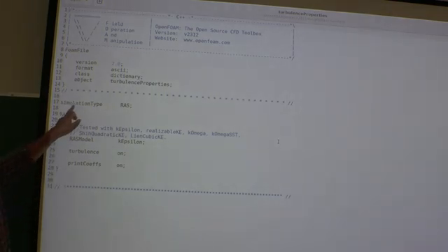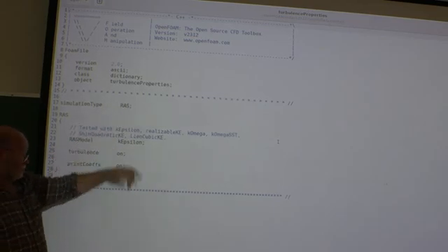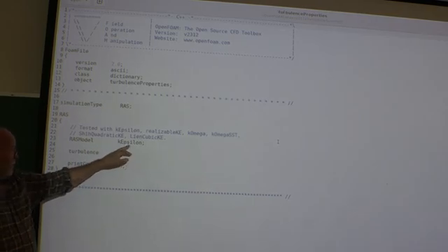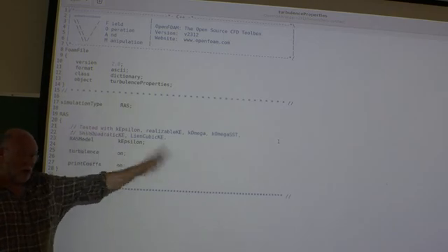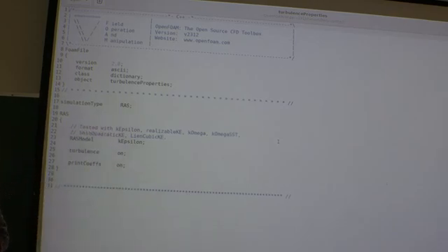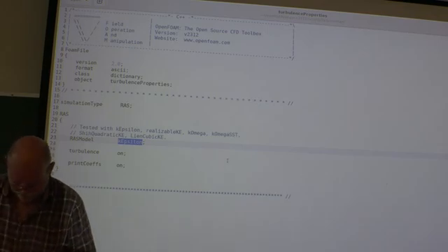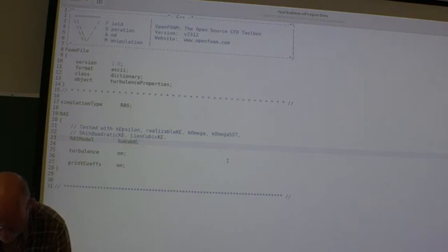Simulation type, Reynolds averaged stress model. And the model we have chosen is k-epsilon. But here you see it's been tested with a whole bunch of different models. So it's a nice tutorial that you can play around with different turbulence models and see the different effects. And also, if you are wondering what model is accessible, you use the banana trick. It's a very good trick. You write something stupid here, and then you try to run it.